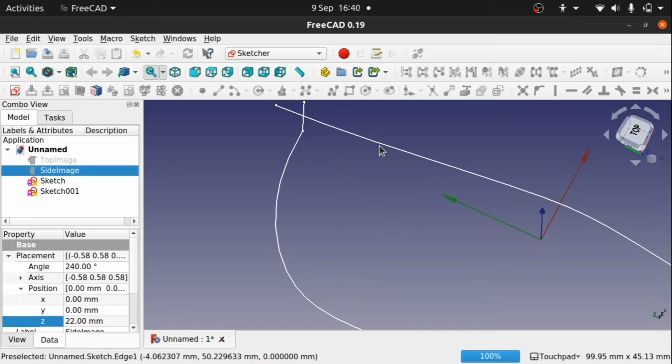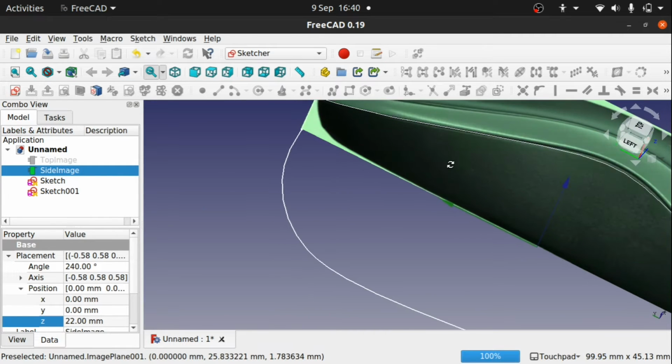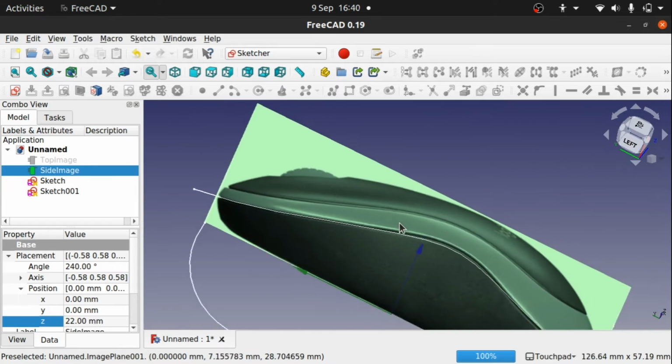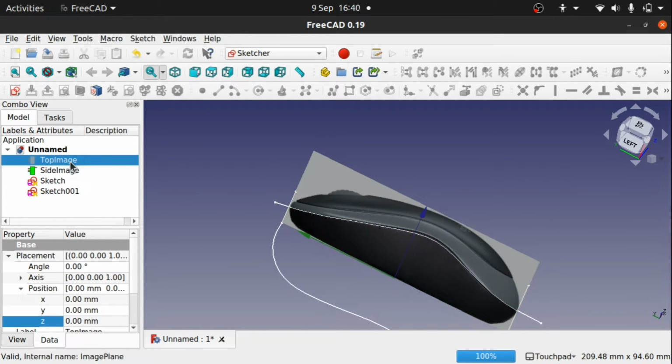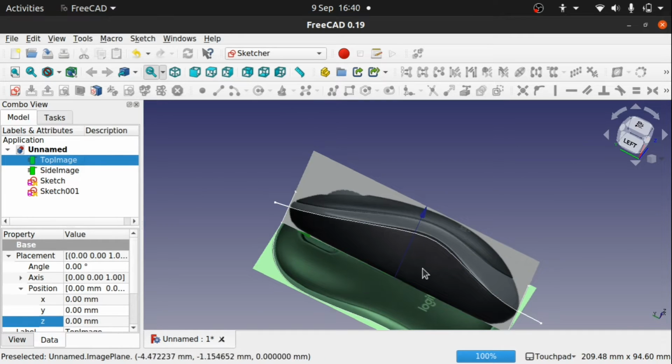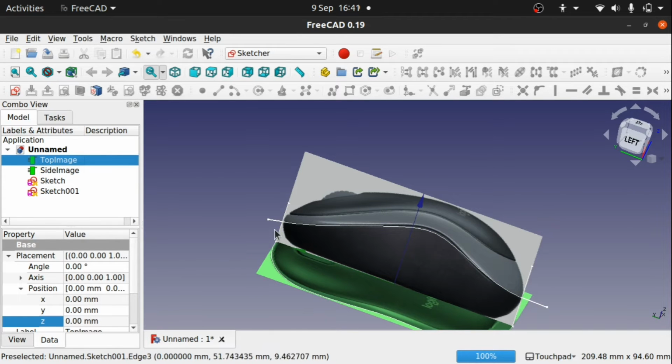and the mixed curve will project. So it will project these two lines into 3D space to around about here, and it will actually connect up to our side feature here in the correct space where these two will actually line up. So it's important that we actually cross that line, because if we don't, the projection may miss that line and we only project part of that curve. We'll see that in a minute.